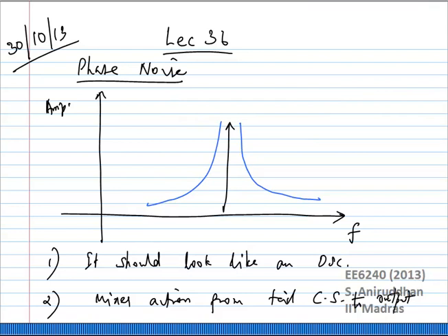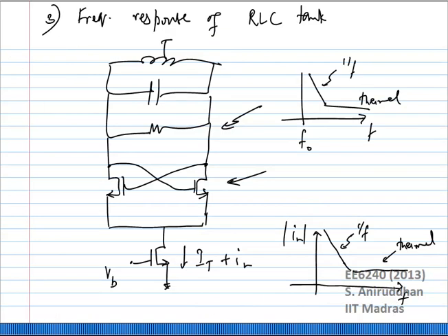If I actually build a cross-coupled oscillator which looks like this, what sets the output phase? The initial condition. Anything else? That is pretty much it, right? There is nothing else in the circuit which actually sets or operates upon the phase of the oscillator. There is something which operates on the frequency, through the control voltage, so indirectly you could say there is some effect on the phase. But if you take just a standalone oscillator, there is nothing which actually directly sets the phase.